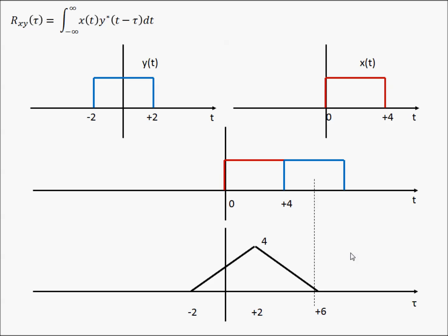The value of the cross correlation begins to decrease, again linearly, out to the point where it's centered at 6. At this point, centered at 6, the value is now 0 again for all delays more positive. So, a couple of things that you should start to recognize are that the peak of this cross correlation is related to the point at which the functions overlap or where they're centered.